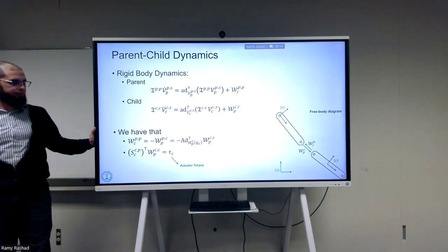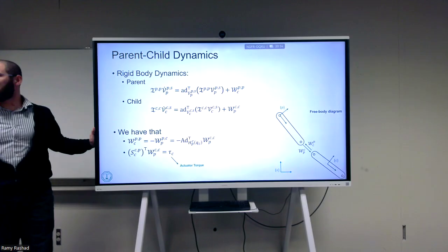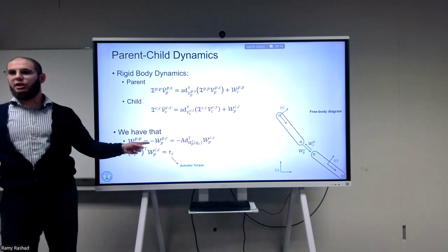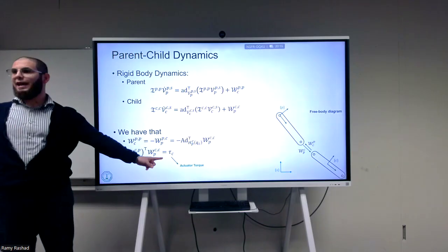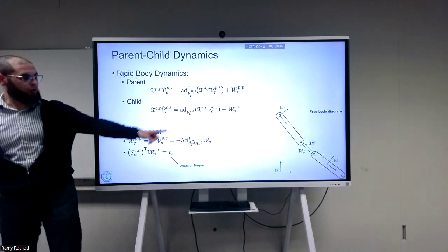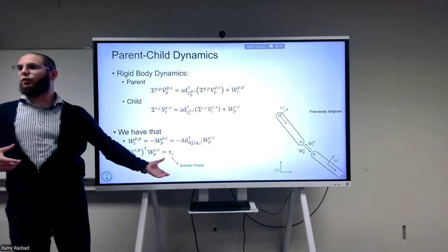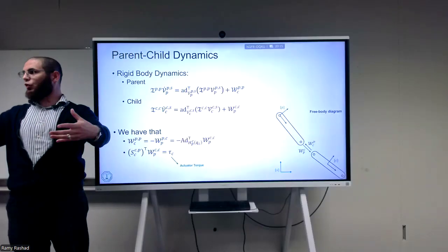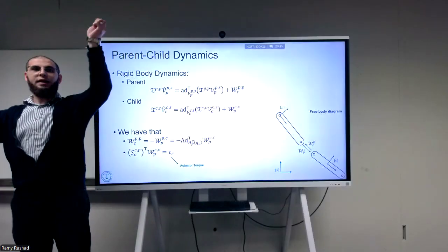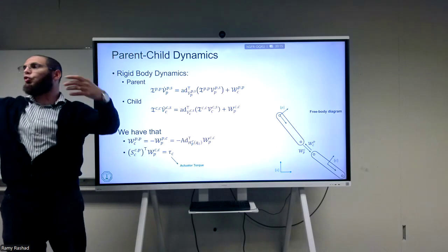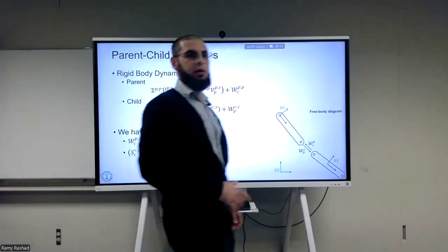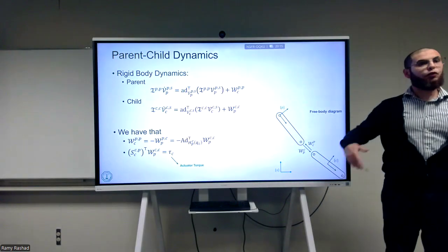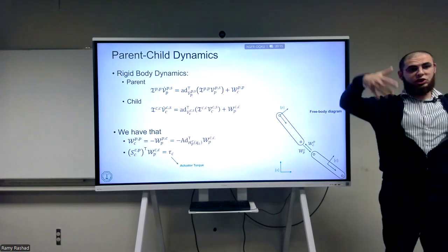Easy? Okay. Another thing, which is exactly what we just mentioned: if we multiply the screw axis by this reaction wrench, you get any actuator torques that you have between these two bodies. And if there are no actuator torques, what do you get? You get zero. It's passive: you just connect the two links, throw one in the air, and the other one is allowed to move with this motion. Okay. So this is all of the dynamics that we need to describe any two bodies floating in the air. They're not fixed to anything. They're just floating in the air.